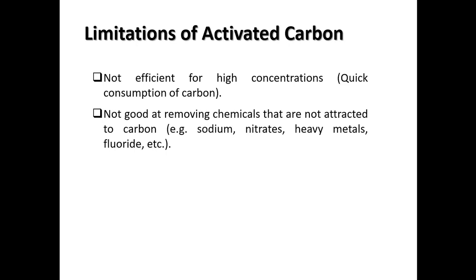And the second limitation is that it's not very good at removing chemicals that are not attracted to carbon. Some chemicals are not adsorptive. They are not so efficiently removed by carbon adsorption, such as sodium, nitrates, some kinds of heavy metals, and fluoride. Those materials normally have low adsorptive ability, so they cannot be removed as efficiently as the other materials.